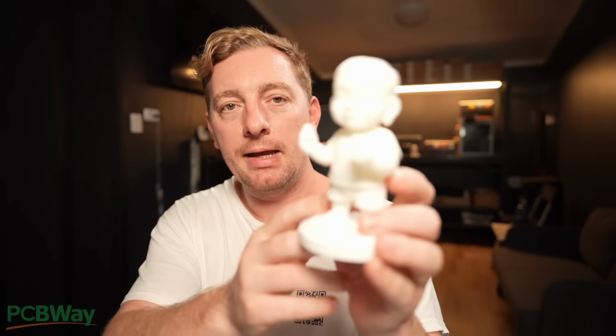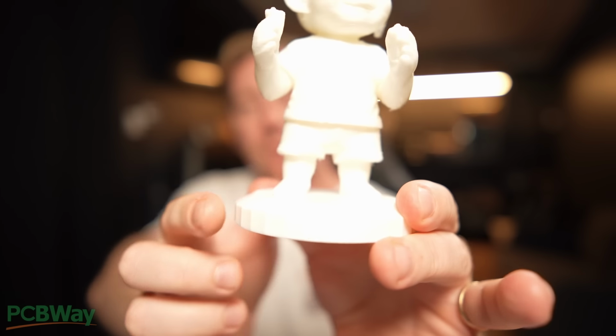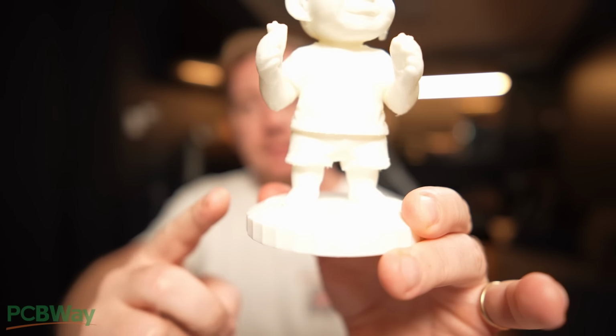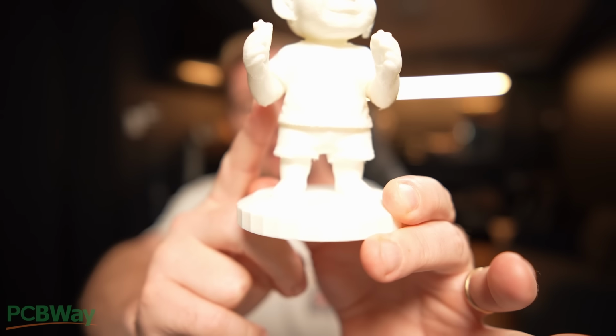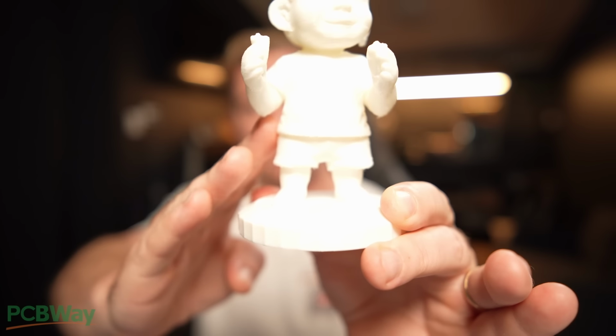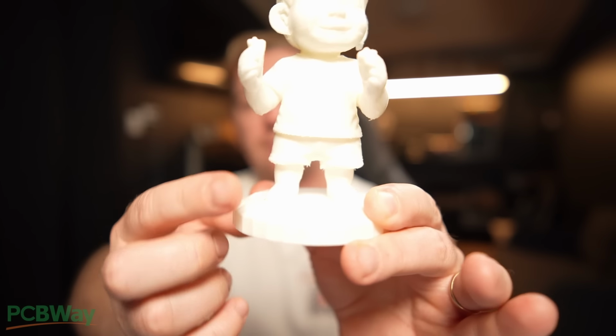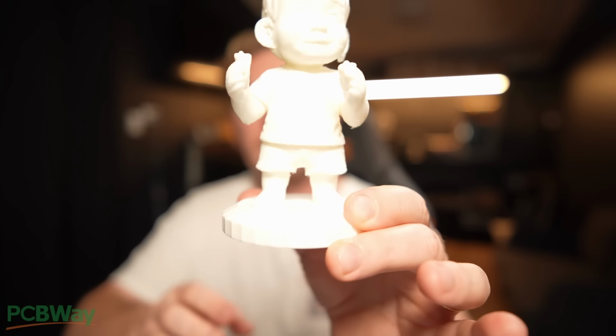Okay, the problem I had with this model is I made the base way too wide. So when the supports were coming up, they had to start from out here to get up to there. And so it had really steep angular tree supports coming in on this model, especially under here, where I had to try and get around this base because I made that base so large. So that's why I think it's important to make the base as compact as you can so that those tree supports can come straight up to where they need to go.